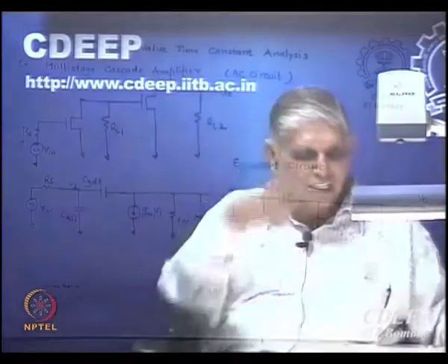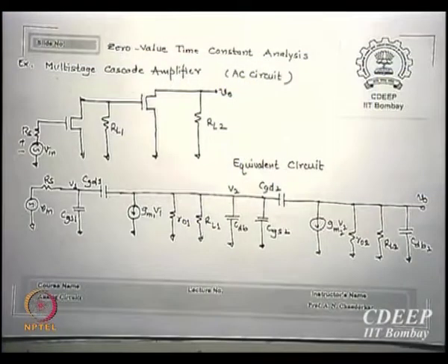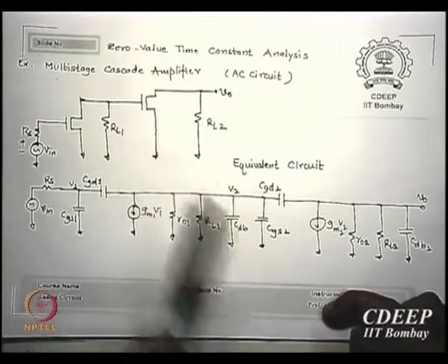Okay. I am not saying this method is always valid. It depends on the values of gm, Rs and everything given, and it may not be the dominant pole which we think. But assuming there is one, I have taken an example which is intentionally a multi-stage amplifier, that is, two cascaded stages of a MOS amplifier. There is a first stage and there is another stage.